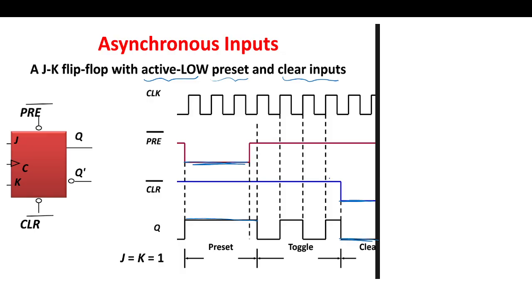So in this, when both are 1 1, it will perform the flip flop operation. And if this is JK flip flop with J equal to K equal to 1, that means it is in a toggle state. So it flips at the positive edge. Whenever the positive edge comes, 1 becomes 0. Again at the next positive edge, it becomes 1 and 0 on the next positive edge.